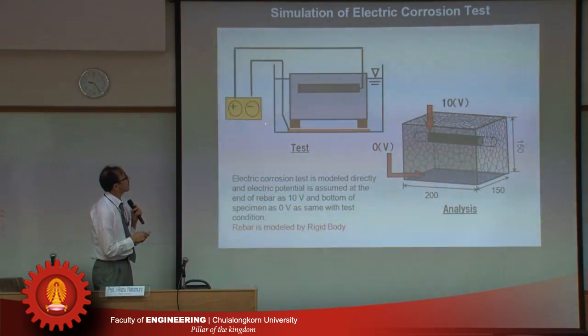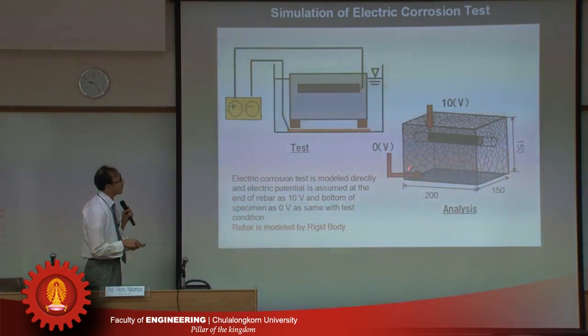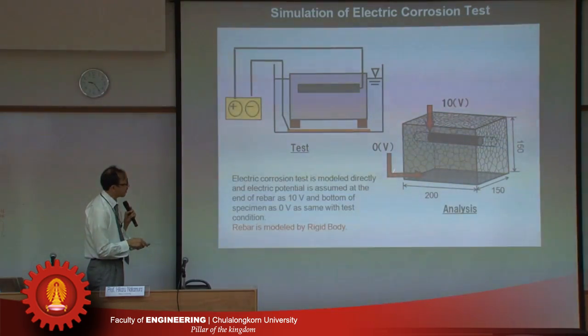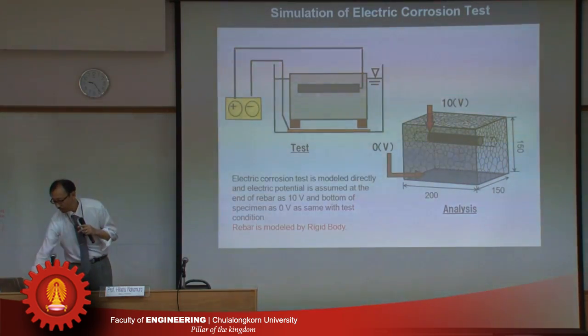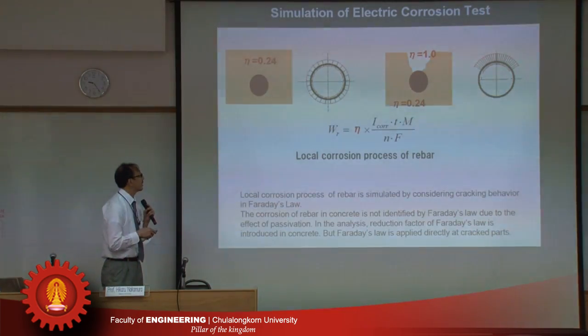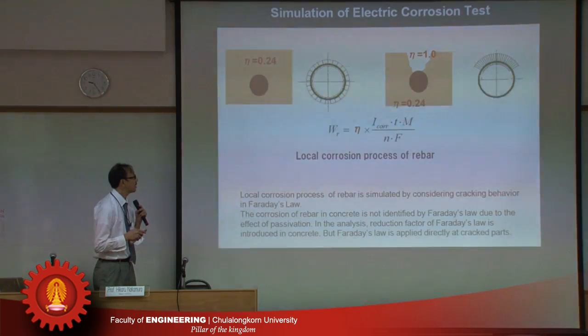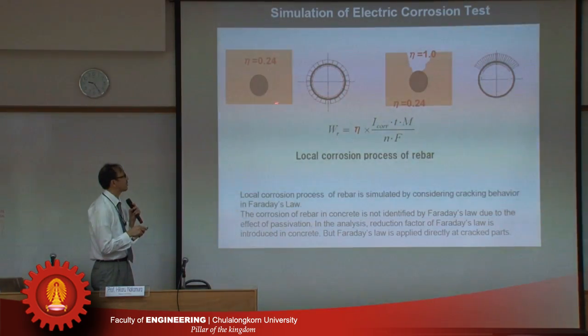This is the analytical model for the test simulation. We consider the electric potentials as boundary conditions. And in this case, the rebar is also modeled by rigid bodies. And one point of this simulation is how to use Faraday's law. Faraday's law is the key point of this simulation.